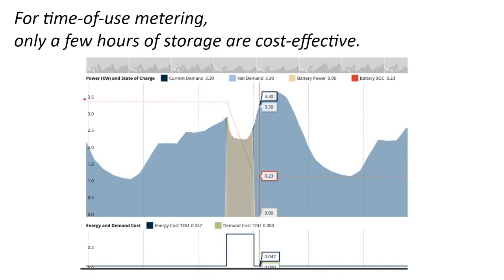And so what that might mean is here's a battery that we wanted to run for 3 hours in the middle of summer, and not buying it to be much more than that. And so we're looking at that one day in summer, on the peak day, the day of maximum usage, and seeing that our battery discharges down to like a 23% state of charge over that period. And we say, okay, we don't need a larger battery than the highest day's use plus 20% margin. That might even be 20% too large for that matter.